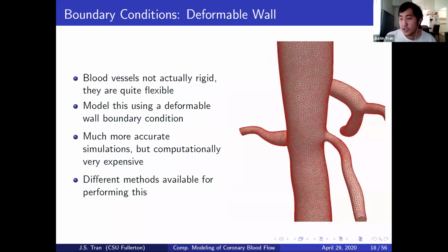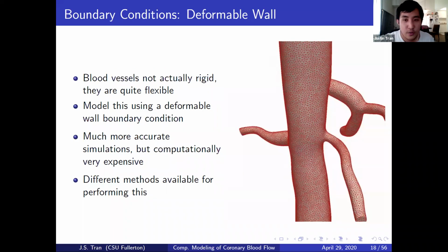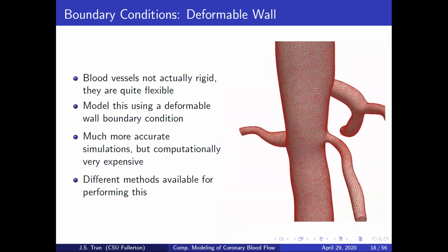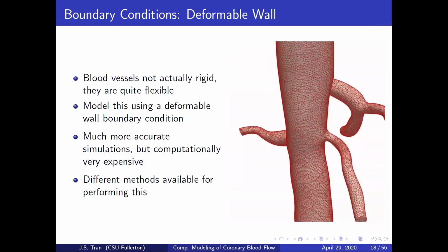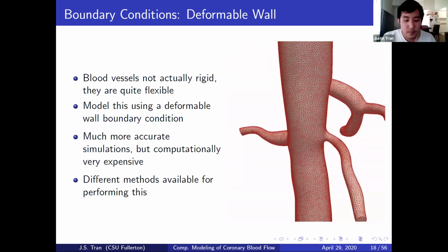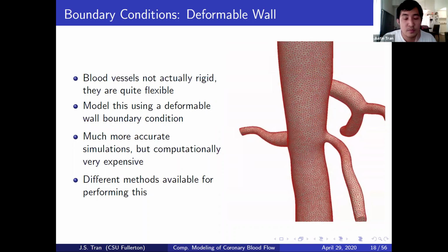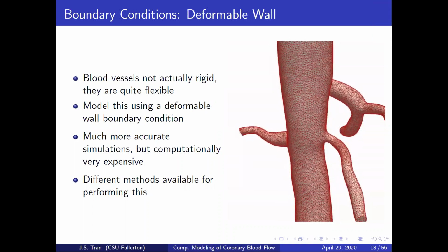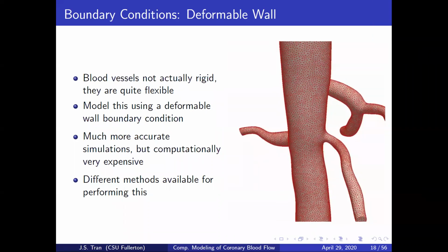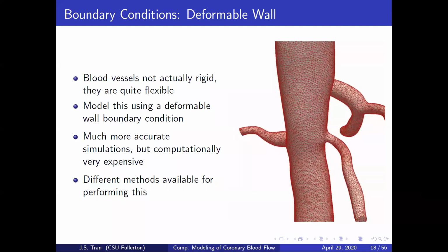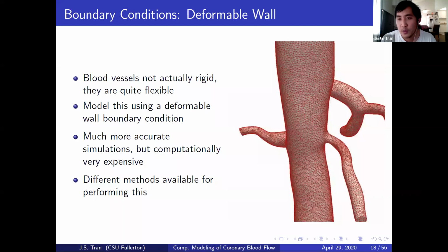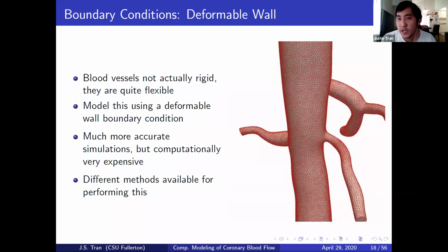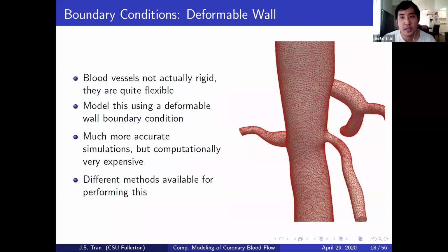Okay, so are there any questions on the boundary conditions or anything that we've covered so far? Yeah, I had one. Sure. Kind of a two-part thing. The second part's based on the first part's response. Okay. At the scale that you're dealing with, to view blood as being a Newtonian fluid, are you also assuming that it's isotropic? Yeah, that's a great question. So yes, we are assuming that the blood is isotropic. We're only specifying a single viscosity and a single density.